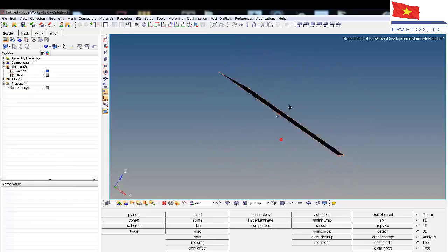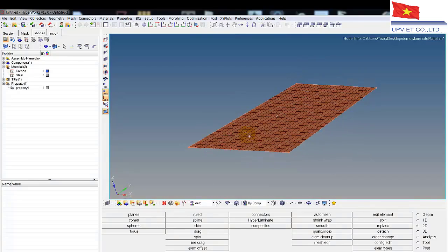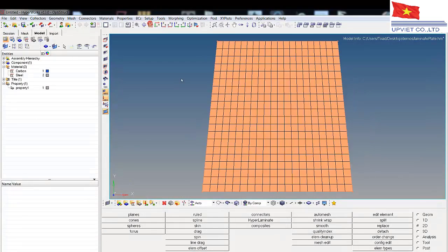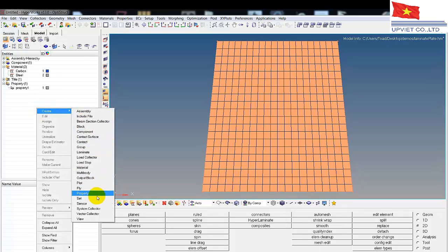What we're going to do now is determine where our plies are going. Now I found in more complicated parts, we'll do it here as well, a very good thing to do is build up sets. So we pick our plies, and our plies are built of combinations of sets, and we can reuse sets. So I'm going to go ahead here and create a couple sets.